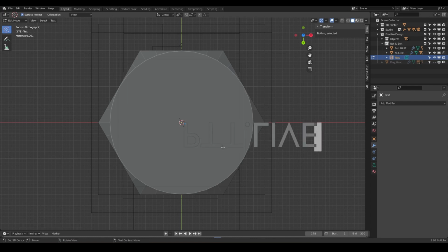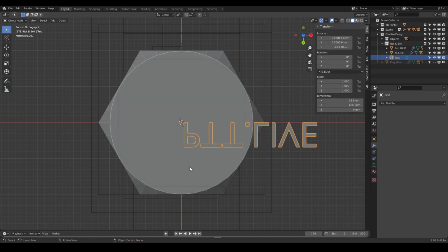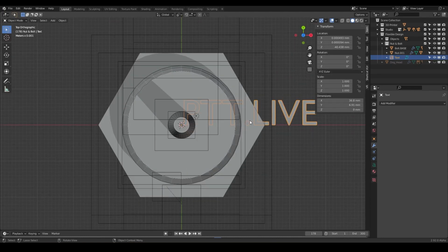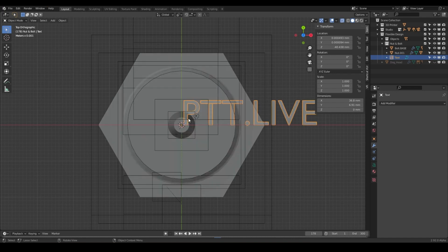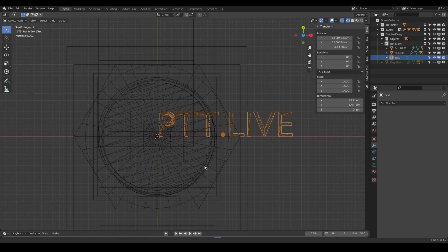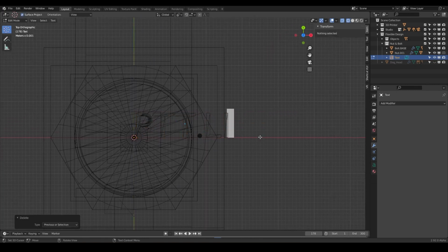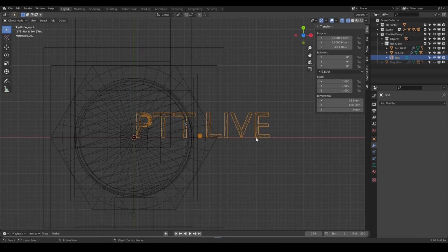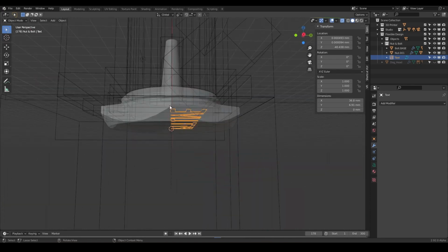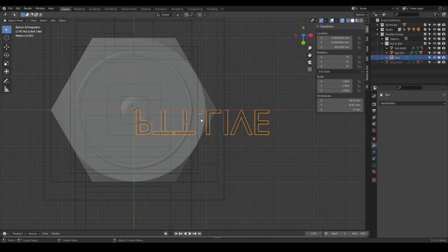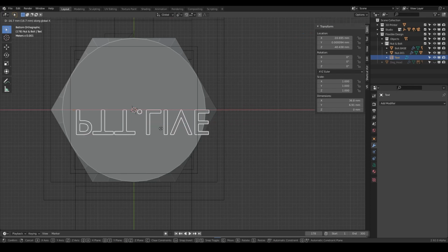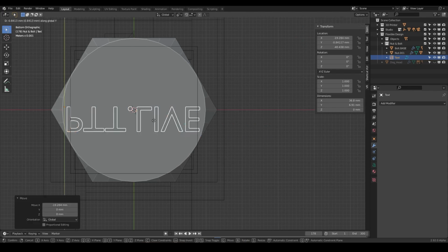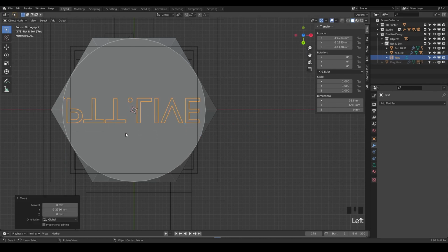That's my website. Oh, it is backwards or upside down. You can go back into object mode, hit 7, and see it from the top there. Or turn on your wireframe or see-through mode, depending on what is going to help you the best. You can go into edit mode and type in anything you want. Notice it's maybe a little too big for our object here. I'm going to turn off the see-through mode and slide the text over, then place it with G and Y. It actually looks pretty good.